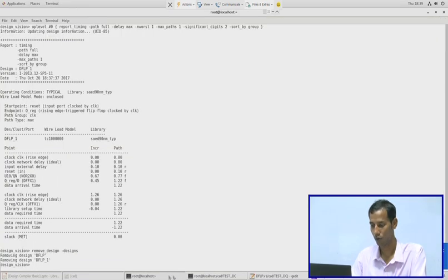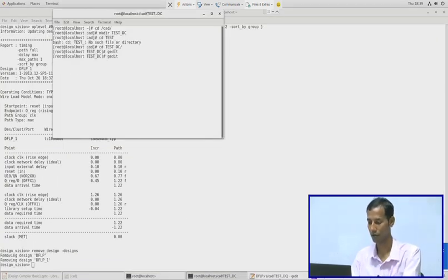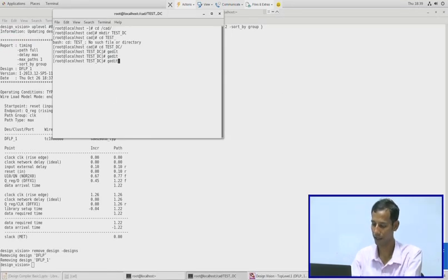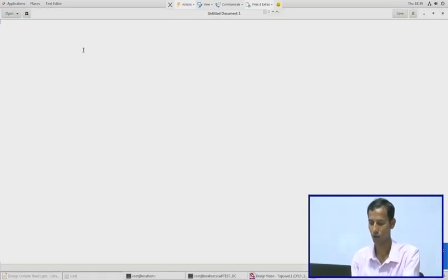Again what I have to do for that, I have to write the code for it. Okay, so now the module name will be count16, then clock, reset, and count is the output, then the input names are clock and reset, the output is [15:0].